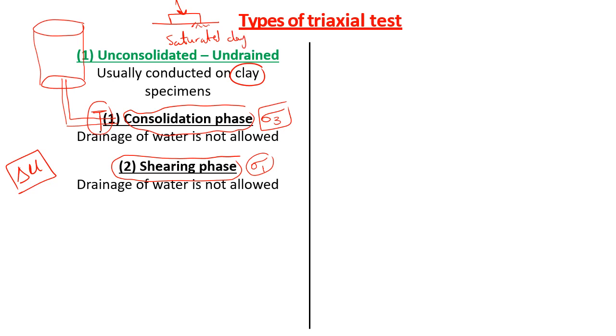The clay has a very low coefficient of permeability, so the water can't move freely. Practically, the clay can be considered impermeable, at least in the short-term conditions. This is for the short-term conditions.